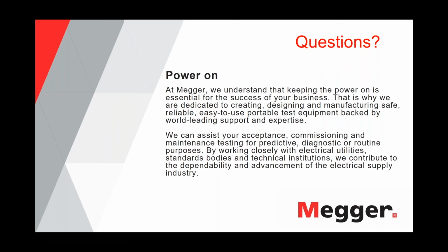By the way, that's an important aspect. People pull an elbow off and do a VLF test, and they suddenly go on a 15 kV cable with maybe, what is the voltage now? 30 kV, right, for testing, if you do a hipot test. So you have to watch, because inside the typical load break elbow, you can get flashover. So what you typically do in that situation is put a plug into the elbow to eliminate the air gap inside the elbow. Otherwise, you might have problems.